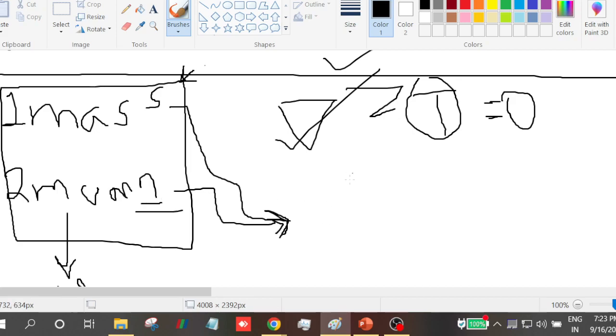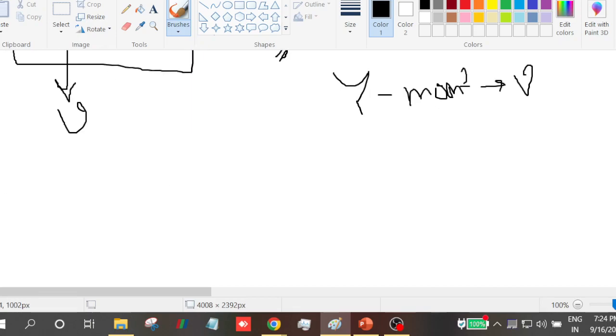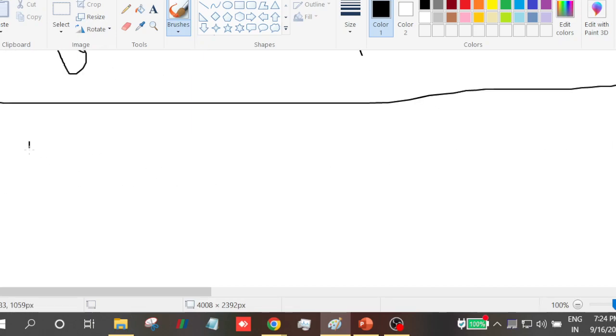The x momentum gives us an equation to calculate the x velocity, u, whereas the y momentum gives us an equation to calculate v, and the mass conservation doesn't have pressure at all. It involves only u and v. So we do not have an explicit equation for pressure. That is challenge number 1, the p equation.